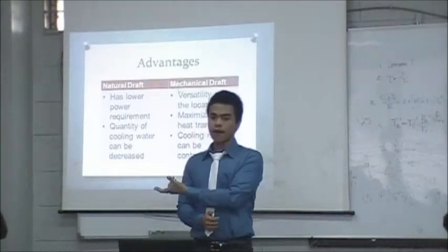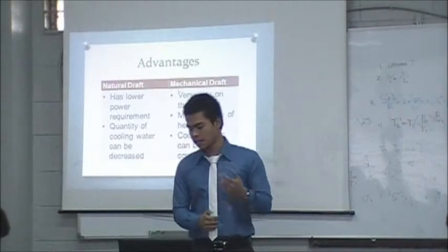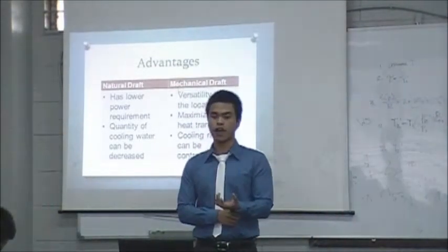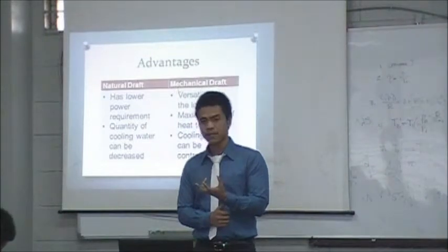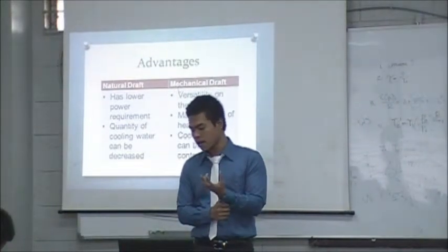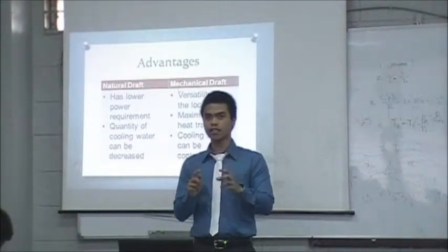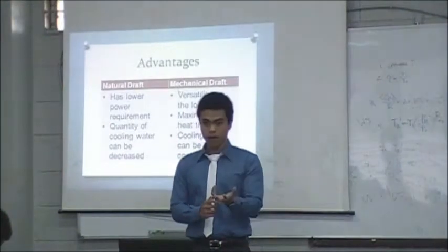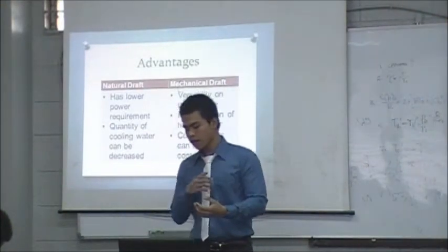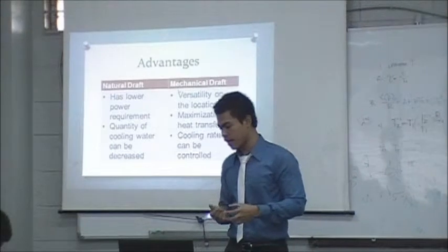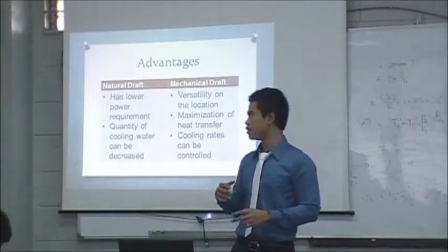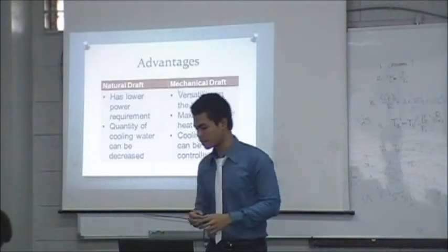And also, an advantage of using mechanical draft is the maximization of heat transfer, because the fans cause an increased contact time between the water and the air. And cooling rates can be controlled by adjusting fan speed, fan diameter, and length.